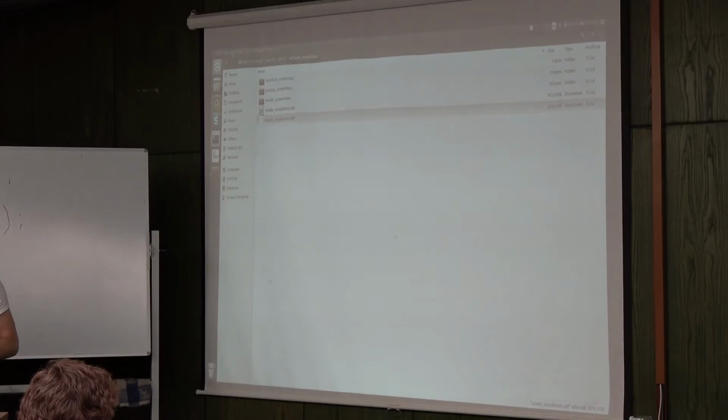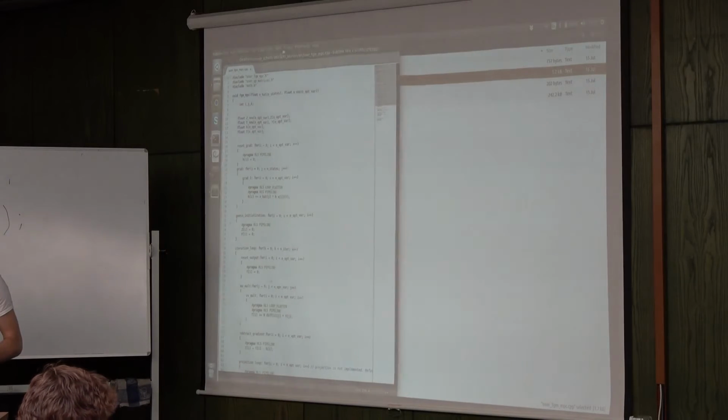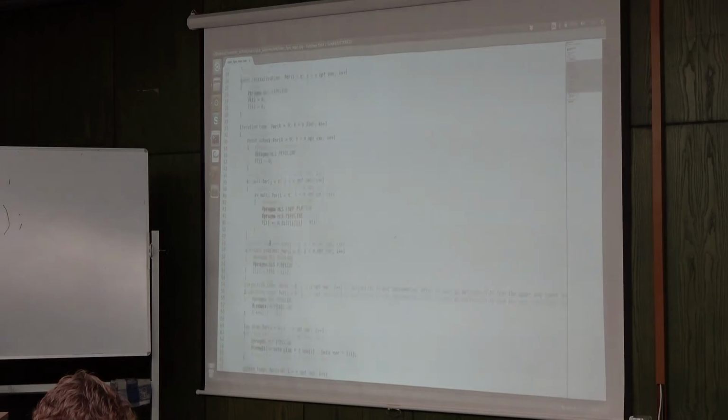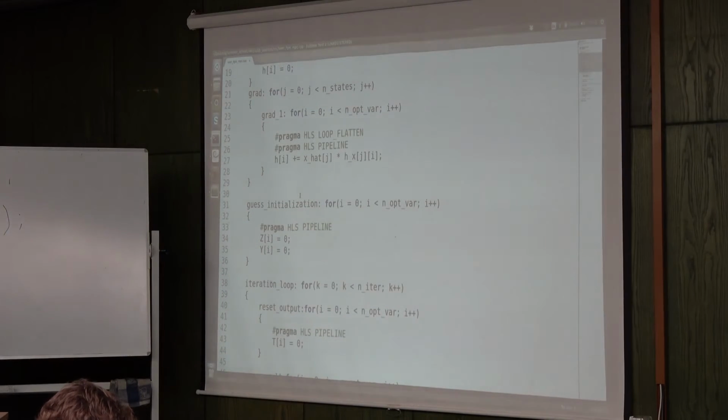And I think I will also go through the C code. This is standard C code, apart from the directives that you provide to the compiler. In this work, we will be using only the pipelining technique. We know what pipelining is. In relation to C code, it is a common approach for speeding up the loops, so that you still have moderate resource usage. It's in contrast to parallelism, when you physically parallelize computations and have to synthesize logic for all the branches. Pipelining works more efficiently, and you will see.